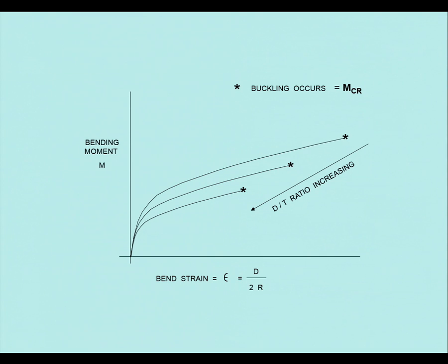There are both loads. When you bend a pipe, take it down to seabed, it'll also have pressure on it on the outside. So it's subjected to both. Which would you expect to fail the sooner? A pipe that's straight with pressure on it on the outside, or a pipe that's been bent with no pressure, or one that's got pressure and bending on? The last one, yeah. So we'll show you how to combine them in a minute.